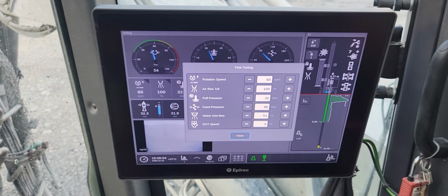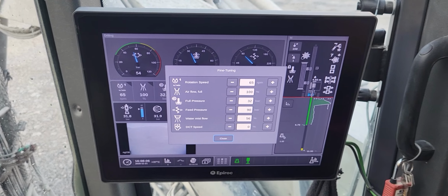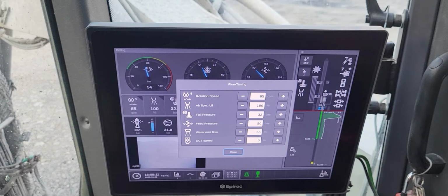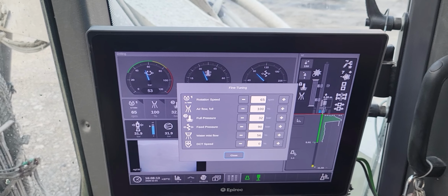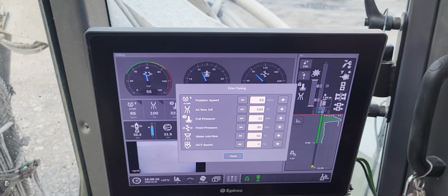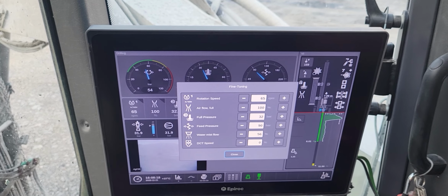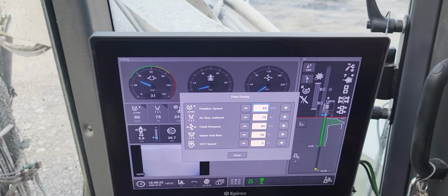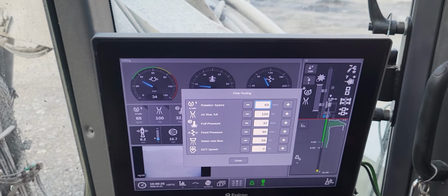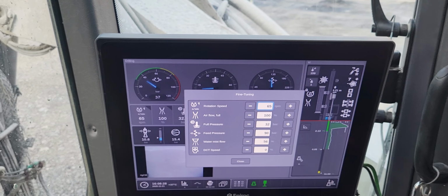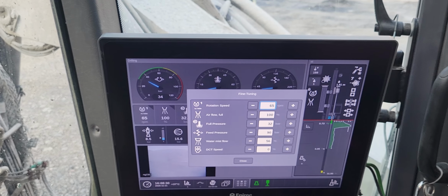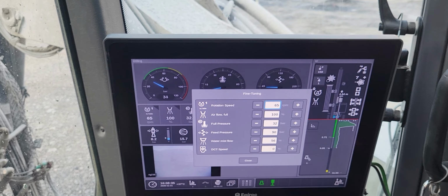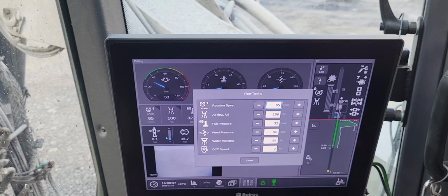It's very important to check that we are using between 60 and 65 RPM. For example, in soft ground we usually see that 65 is a very good RPM, gives a high penetration rate and not too much wear on the buttons. Sometimes if the rock is harder, we go to 60, 62, so we decrease the rotation speed a bit. That gives a bit more meters on the bit.